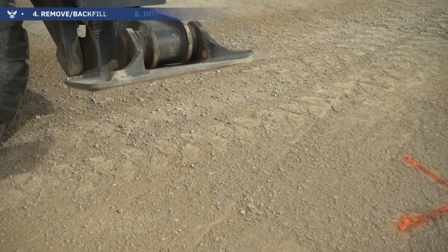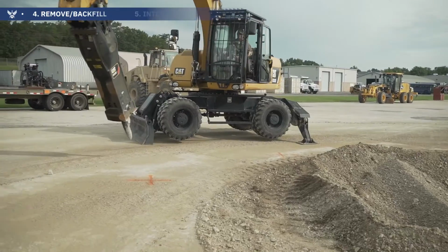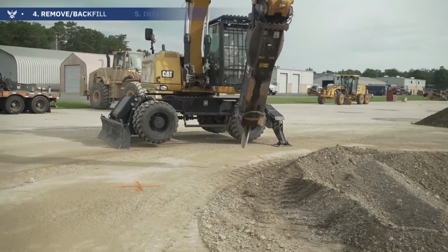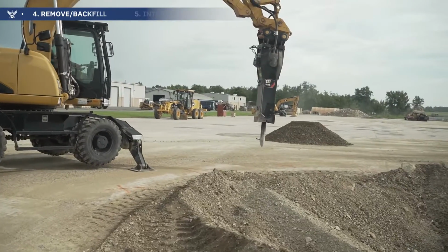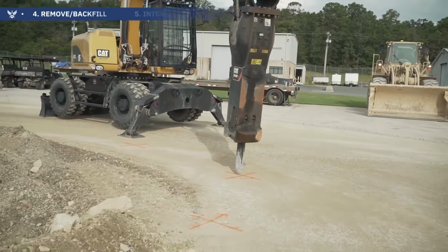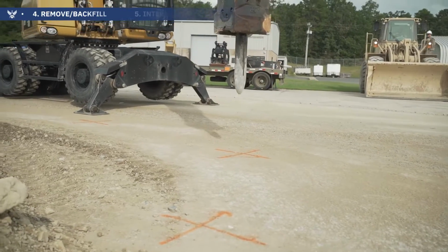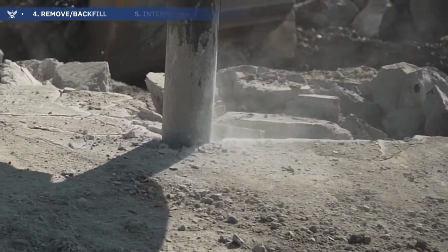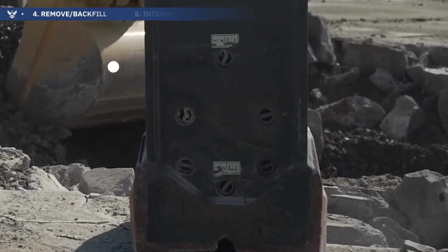Step 4. Remove upheaval, excavate, and backfill. Debris backfill crater repair method. Using the excavator, break and remove the pavement in the crater bottom that exceeds 3 feet in diameter. Using the excavator bucket or moil point, begin breaking and removing the upheaved pavement to marked upheaval limits.